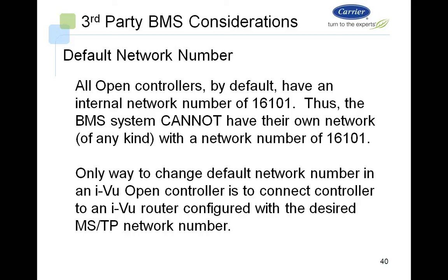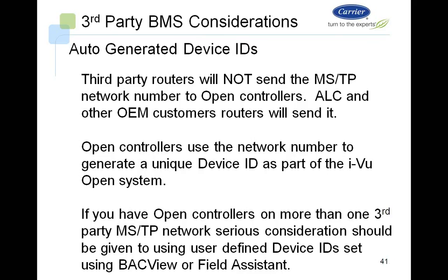Typically, third-party routers will not send the MSTP network number to open controllers. The exception to that is other ALC or ALC OEM customers who use a router similar to what we have. Those will also send their network number, and that will be accepted and processed by open controllers.